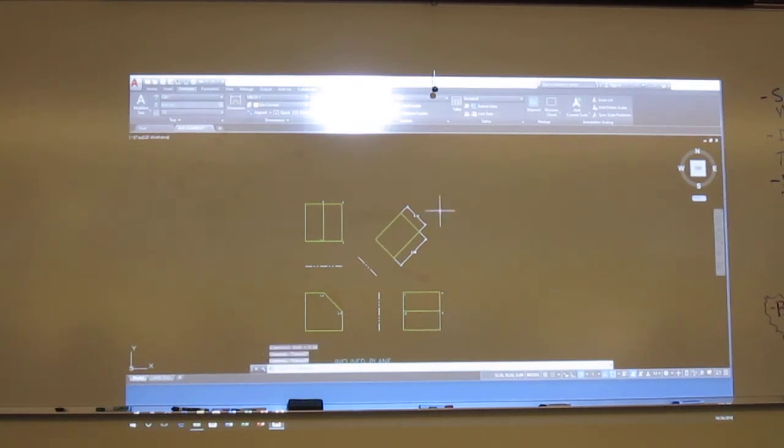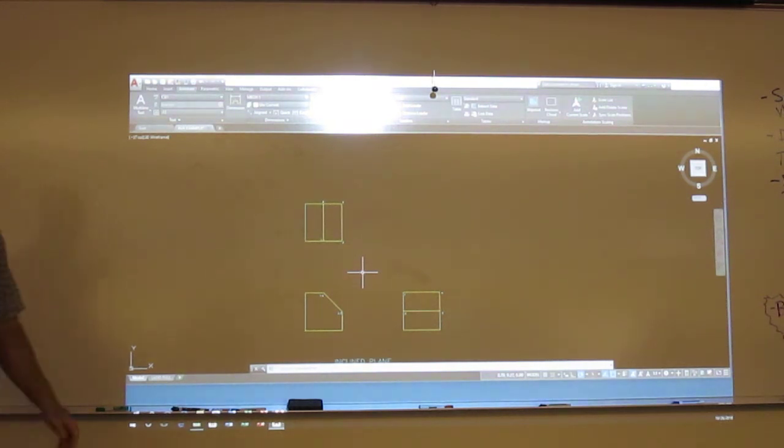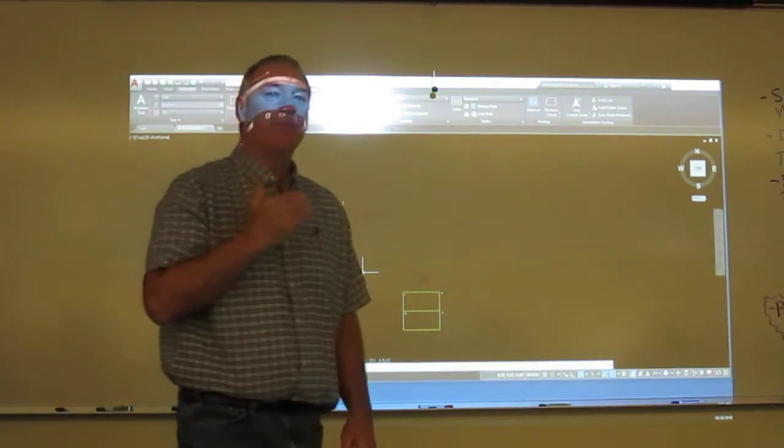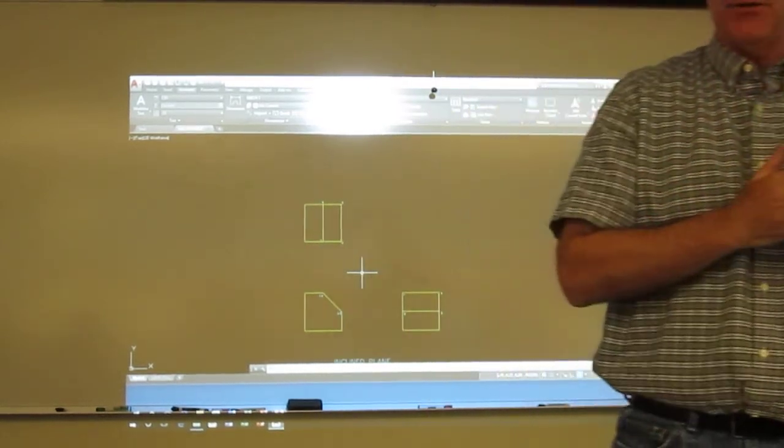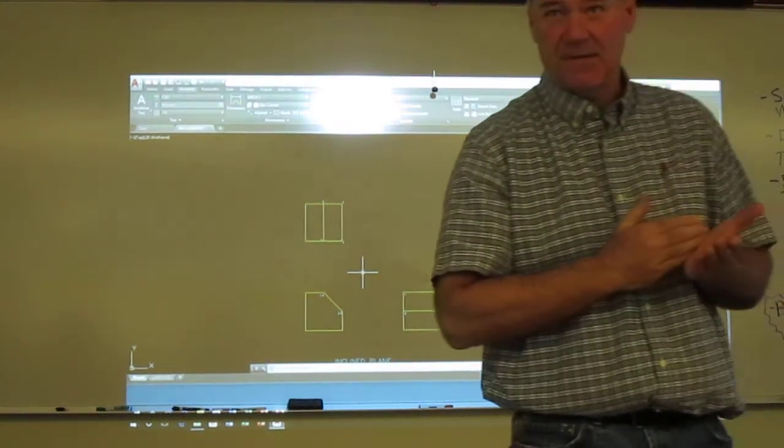And to get it set up again, if you would, just go ahead and delete everything that we did out of it so you're back to the original. Now with the reference plane, remember what we do here, what we just looked at in those figures. You pick a plane on the object that you see as an edge to transfer depth dimensions.